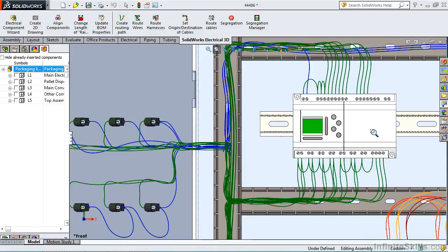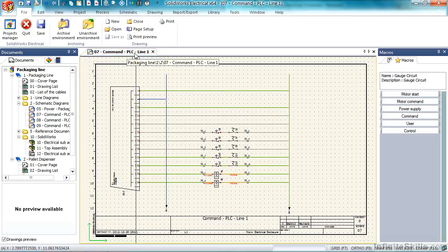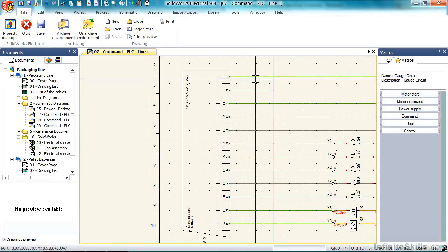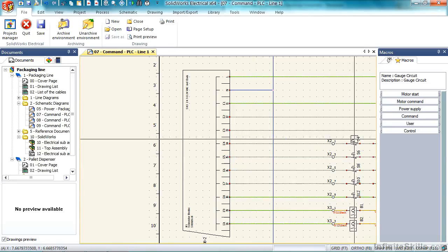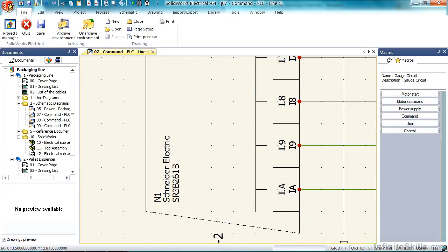without good documentation. Imagine a more complex PLC, a rack-mount PLC with many modules. Here is a schematic representation of what the electrical installer will see. On the left-hand side is the same exact brick-style PLC, and all the wires connecting to it. Notice that each port is labeled, and each wire type is fully described, and we have a ladder logic diagram showing what the actual circuit in the PLC is programmatically doing.